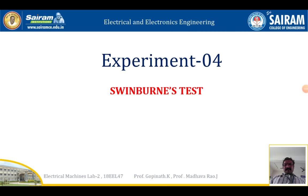In electrical machines lab, Swinburne test, experiment number 4. The Swinburne test is an indirect method for determining the efficiency of DC machines. It works by finding the no load losses experimentally and then estimating additional losses from the rated motor data and generator data. From this information, the efficiency can be determined at any applied load.